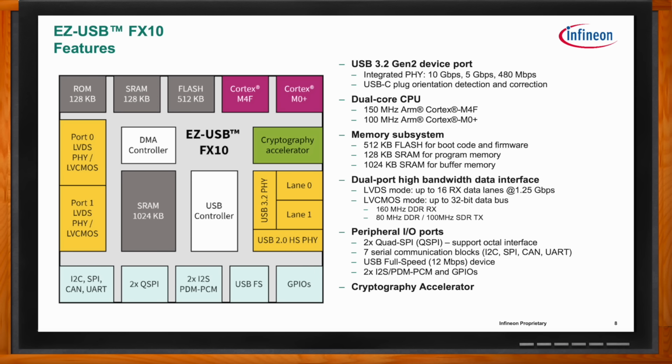We also include a cryptography accelerator in the FX10, so you can do encryption and decryption for your data. Lastly, we kept the package the same as FX3, a 10 by 10 BGA package with 169 balls and 0.75 ball pitch.